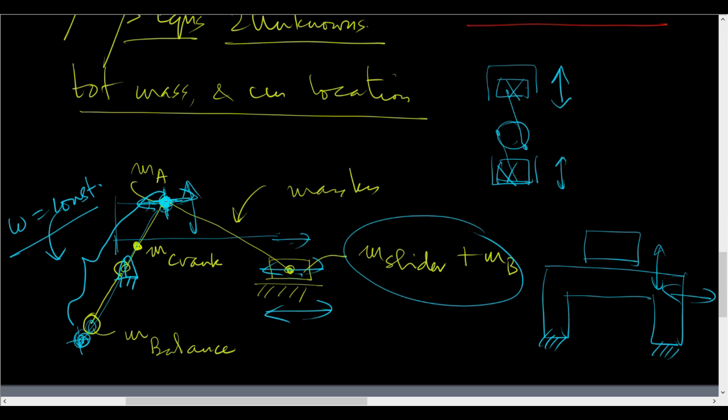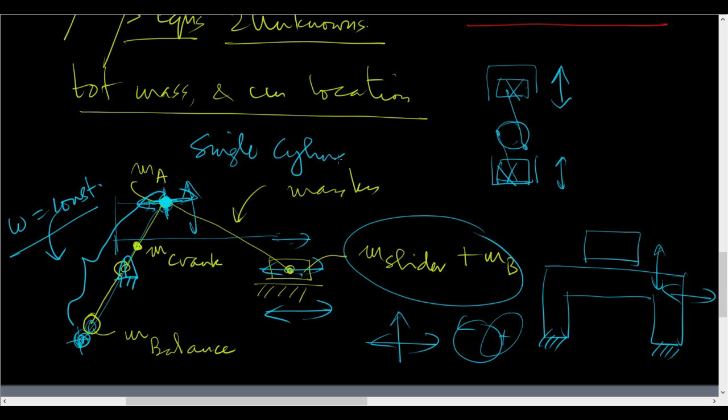Okay, because the horizontal part will be cancelled. In this way, this unbalanced force can be changed to this unbalanced force, or a rotating unbalanced force, or some effectively elliptical force, okay, at some angle. And people, for example, single cylinder motorcycle engines, right, they pay attention to these things.